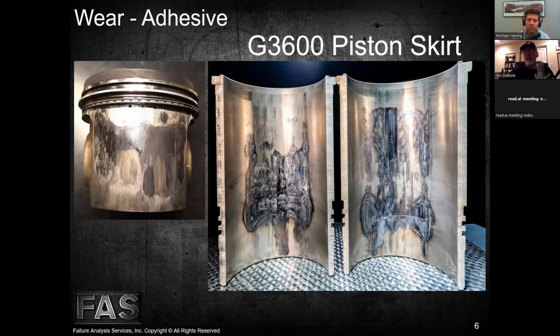And the way that I like to think of that, Michael, is what are lubricants doing at those temperatures? The reality is that at 400 to 450 degrees, the lubricants are extremely thin. Some lubricants are possibly reaching their smoke point. At 600 to 900 degrees, the oil is starting to carbonize. So now we're just generating carbon, and the lubricant film is evaporating essentially.